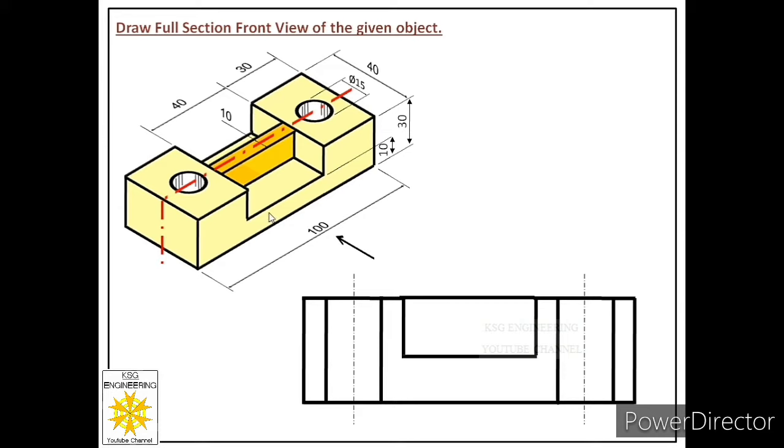But over here we have to make one very important observation, that this plate is a rib. We have learned in the first lecture of sectioning chapter about ribs, and we learned that if we have a rib in a particular object, we never merge the rib with other plates of the object during sectioning process, and we never place section lines in the rib area, though we cut the rib during sectioning in this particular example.